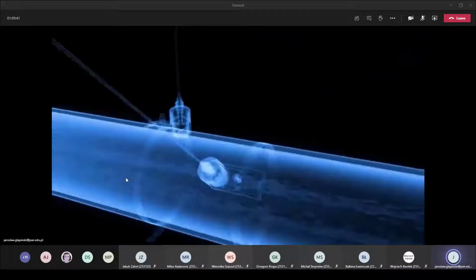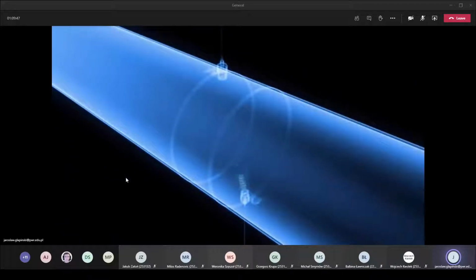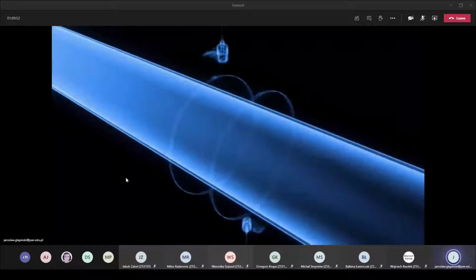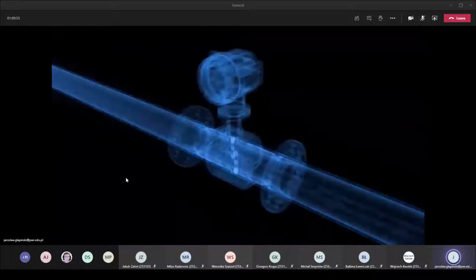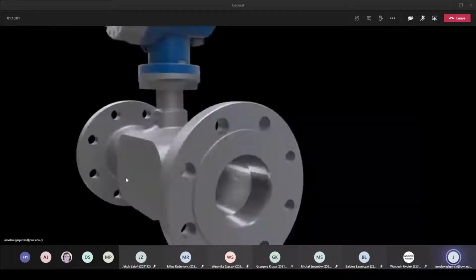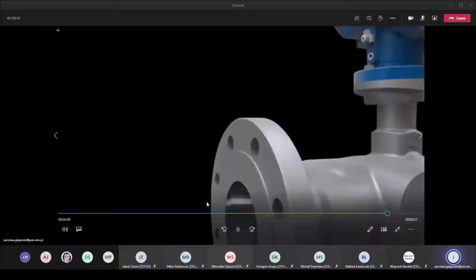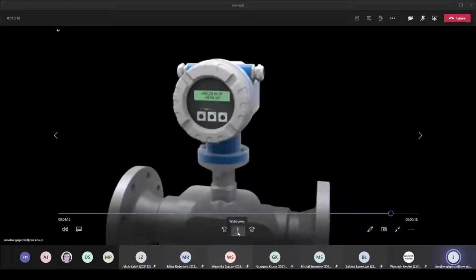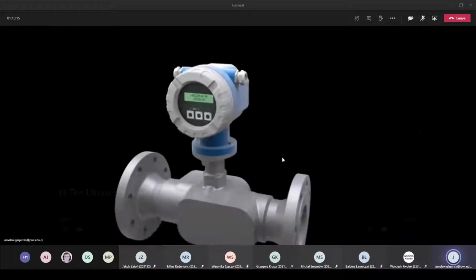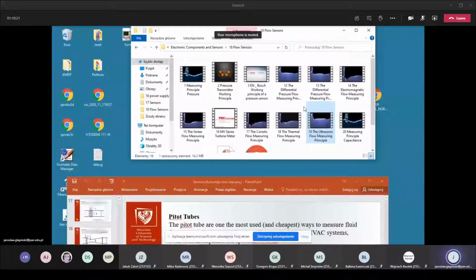The clamp-on design is unique because flow rates can be measured in very large pipes, up to 4 meters in diameter. This possibility increases the areas of application, for example in the water and hydroelectric industries. Flexible mounting, process safety, and cost effectiveness are the distinctive advantages of ultrasonic flow measurement. Okay, so that was the solution, how we can measure flow using ultrasound signals.